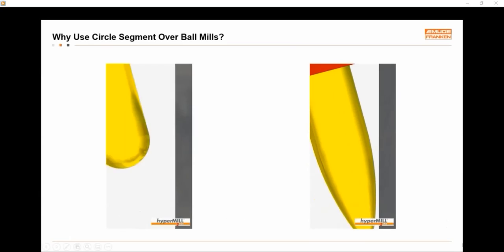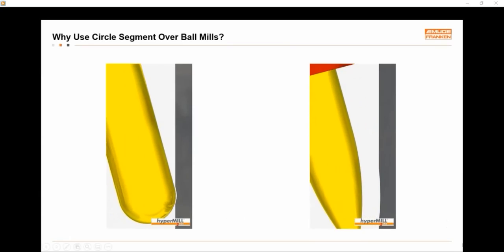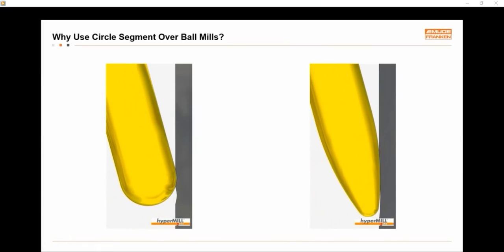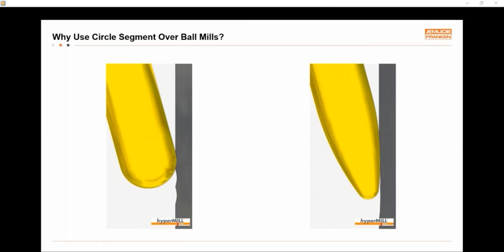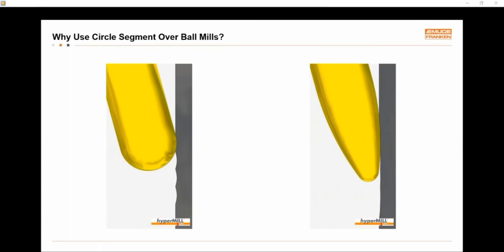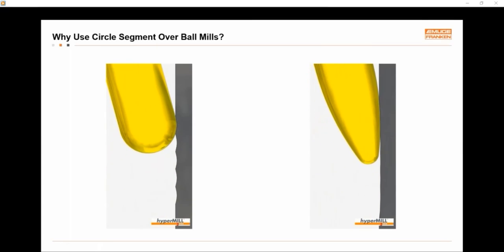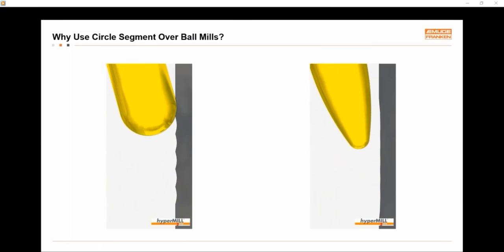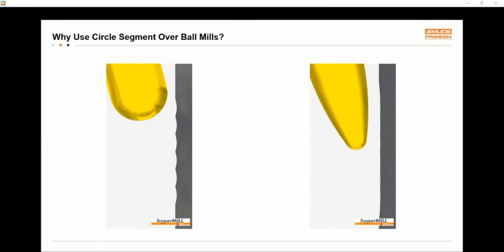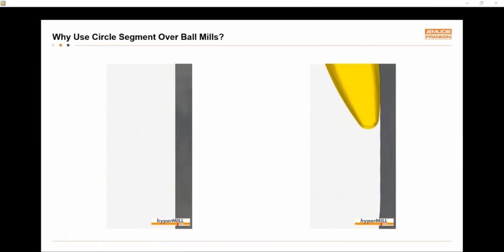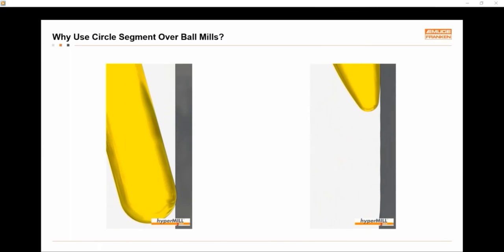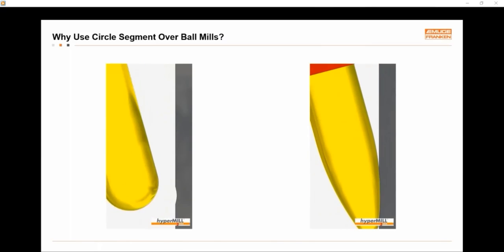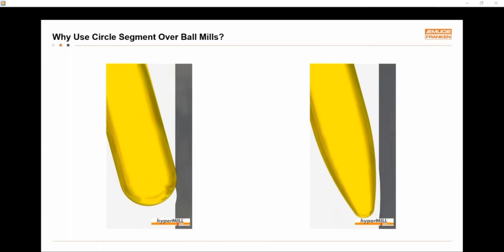And there we go. Now they're playing. So on the left here, we have a 1/2-inch ball end mill, and on the right, we have an oval form. You can see that both tools are just doing a zigzag motion here, and they are both doing the same step over of 1/2 millimeter.